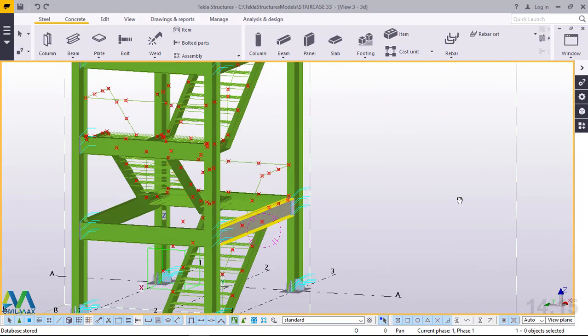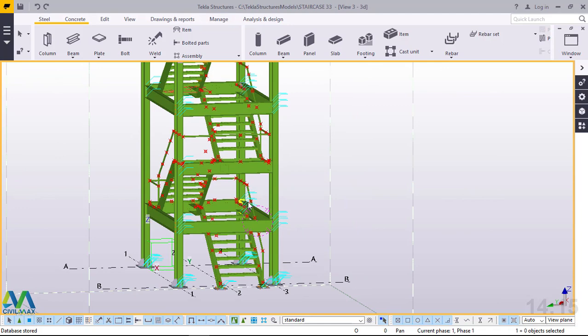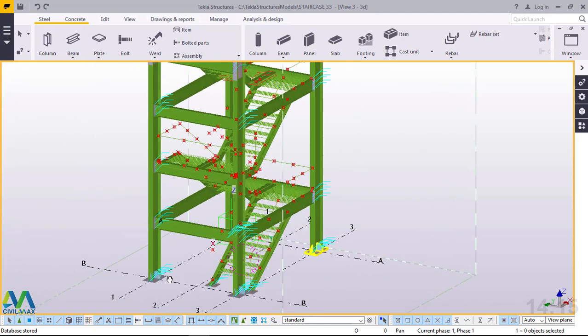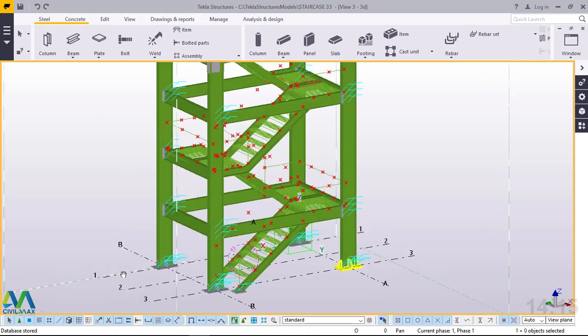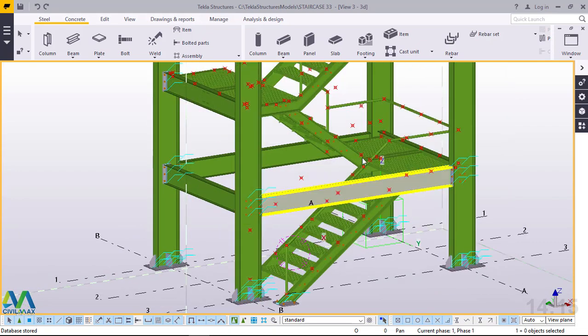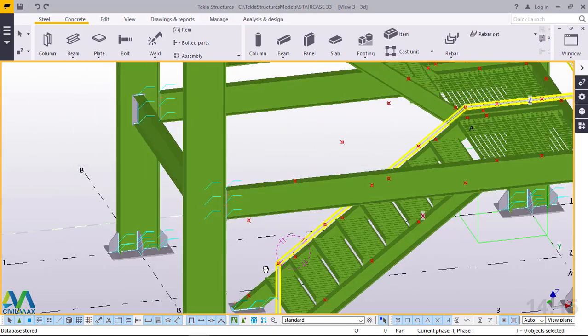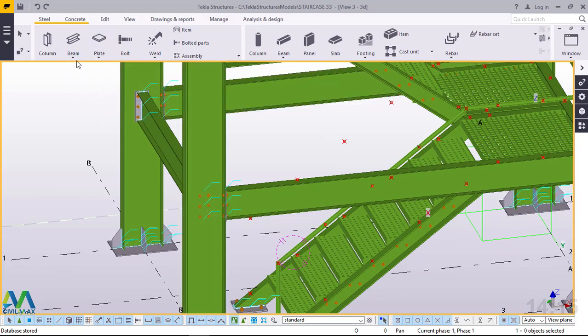Now I've made this, and I want to come to this end. I'll turn this round by pressing the control button on my keyboard and the middle button on my mouse, holding both of them and moving my cursor. This will move this perfectly. I'll come back to this point. I want to create the other end of my handrail on the first flight of the staircase tower.